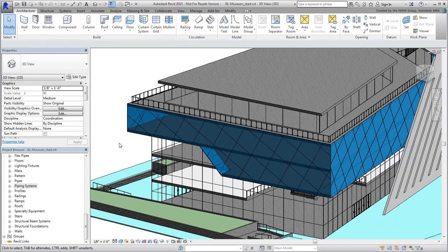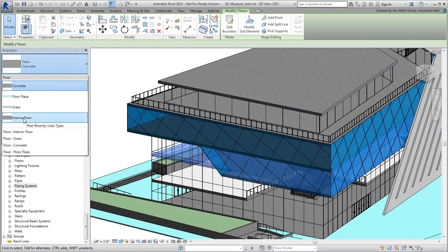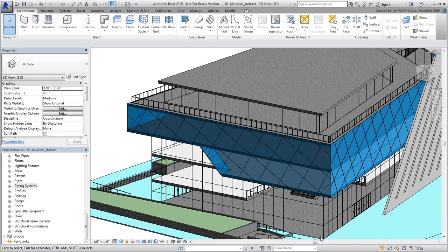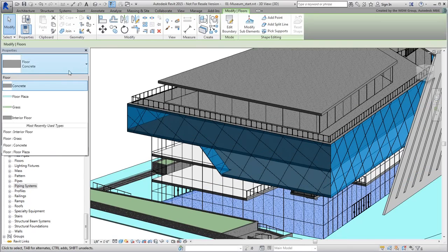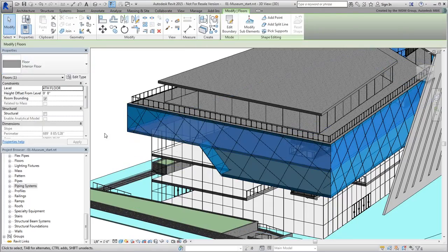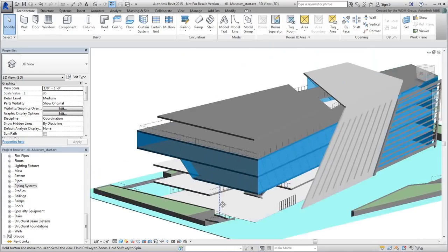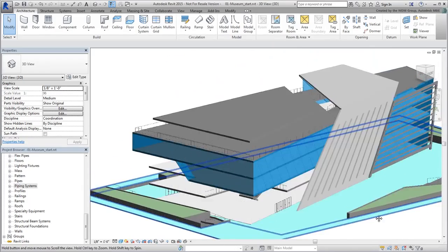Deselect the floor and notice how it's now different from the others in this project. Now that you have defined a new floor type, both in structure and in material, you can select any other floor and painlessly switch it to the new type. While it's good to fine-tune materials in Revit, sometimes it's easier to leave that task to 3ds Max. In some cases, editing materials in Revit can be somewhat convoluted. This is mainly true when dealing with hybrid components.